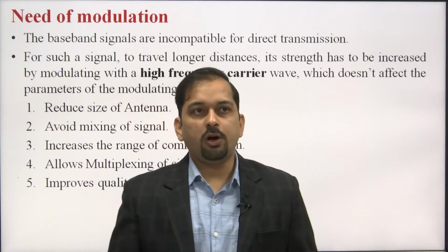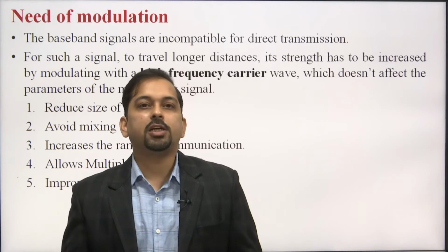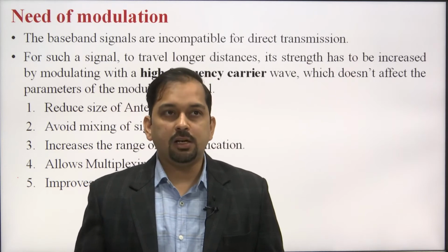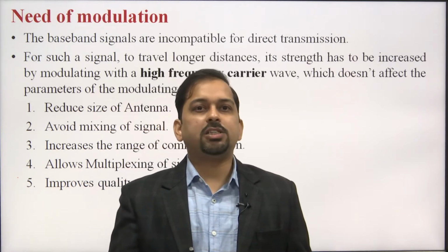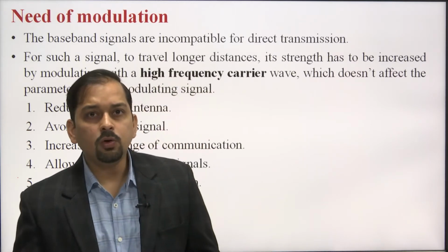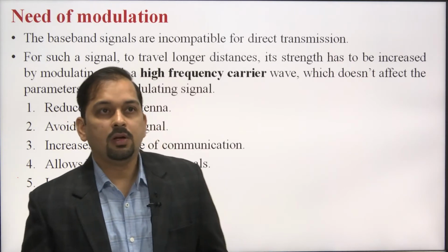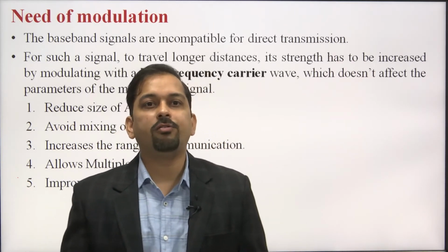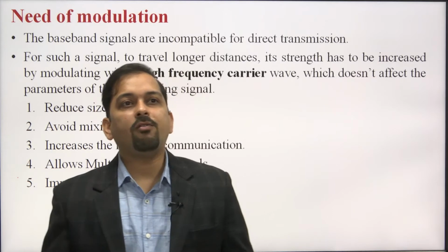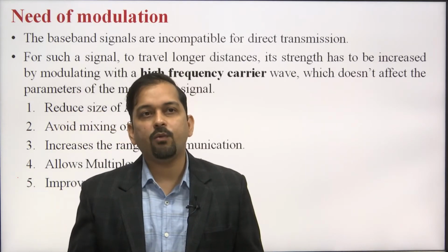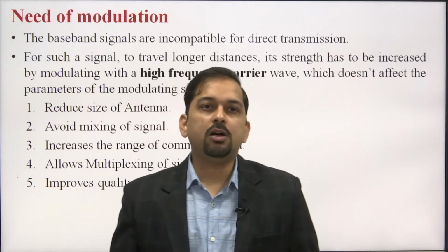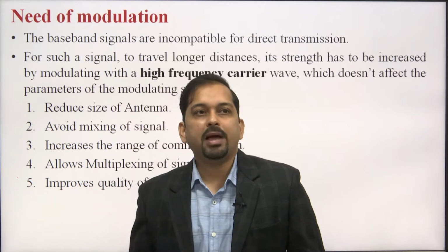So now what is the need of modulation? Since the baseband signal or the message signal is not compatible for direct transmission over the channel, for these signals to travel long distances, their strength has to be increased. If we increase the strength with the help of the modulation process, with a high frequency carrier signal, it does not affect the parameters of the modulating signal, which is called the message signal.